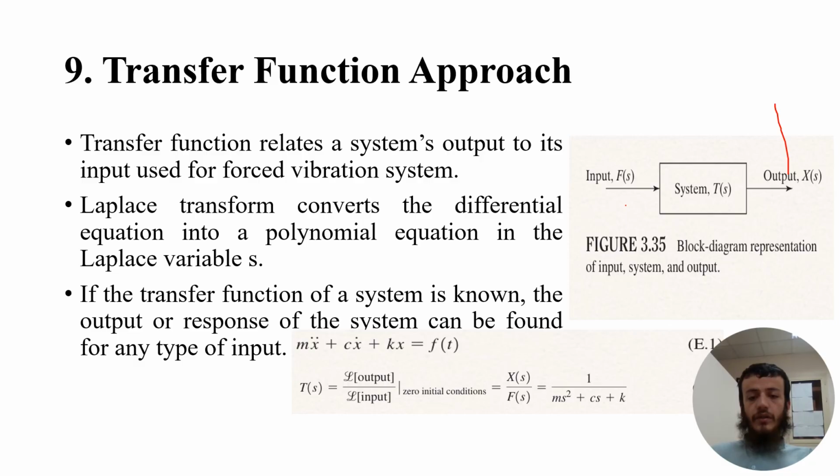If we suppose this equation, how do we convert it to the transfer function? Simply take the Laplace transform of all the terms of x, considering initial conditions as 0. We will have s squared, s, and 1 here. The common factor is x.